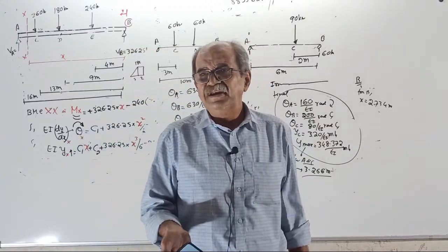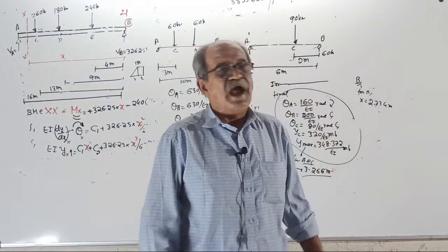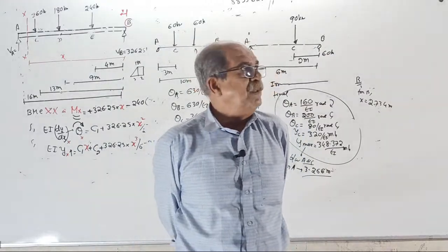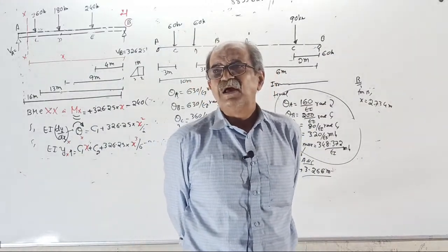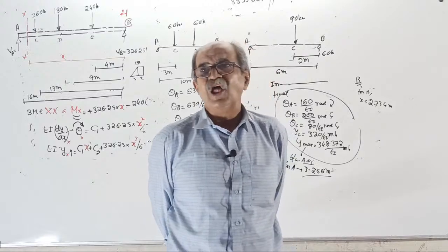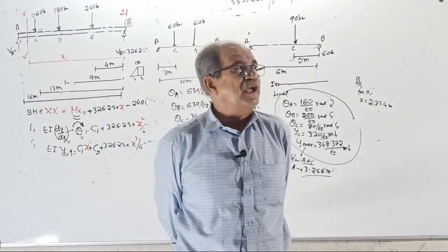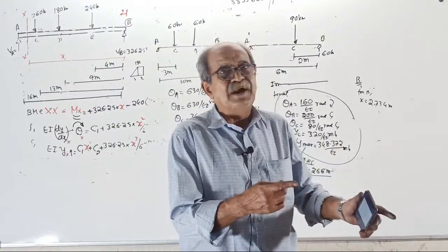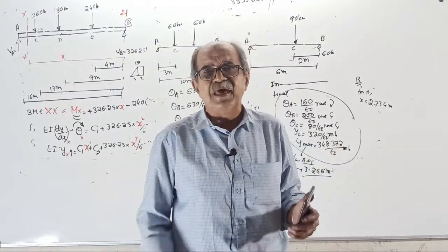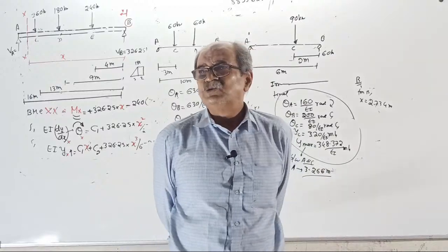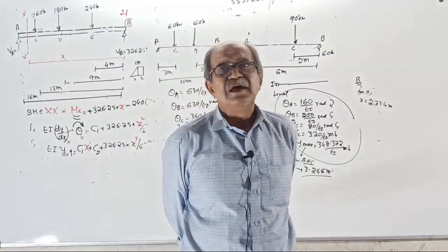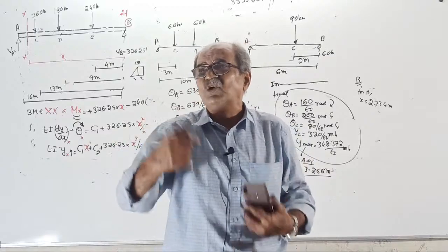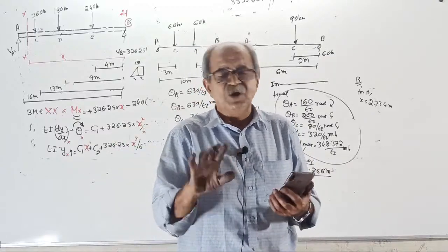Actually, even indeterminate structure you don't know. I actually use slope deflection method, Kani's method, and moment distribution method, along with the column analogy method, sometimes matrix method. I mix them all. Whichever I feel comfortable, that part I will take from there. Sometimes, once you get one answer, some other method gives you direct solution. That is the trick only.